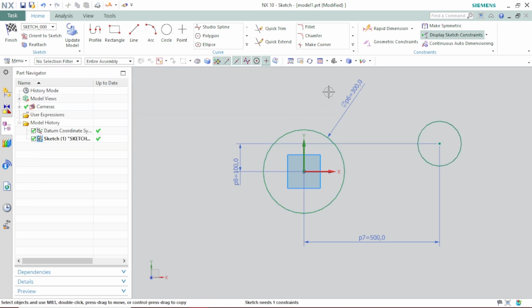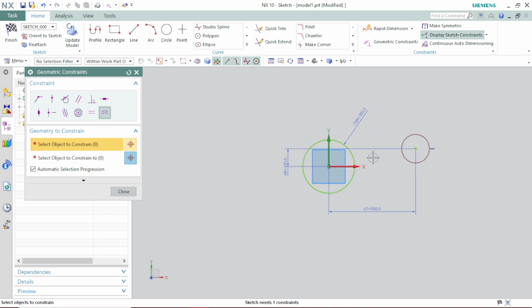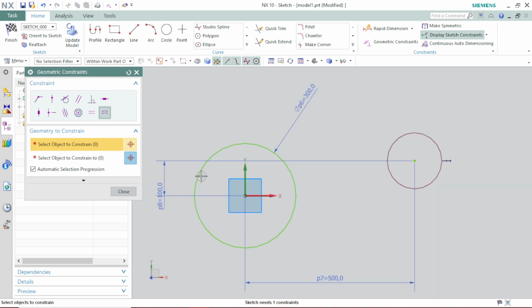Okay, so after that, if you assign the geometrical constraint, for example here equal radius I will apply to this circle. As you can see here, we have specific dimension given here, so it is a specifically defined one. So if in the first selection I select this one, okay, and in the second I will select this one, okay, so this radius has been changed.